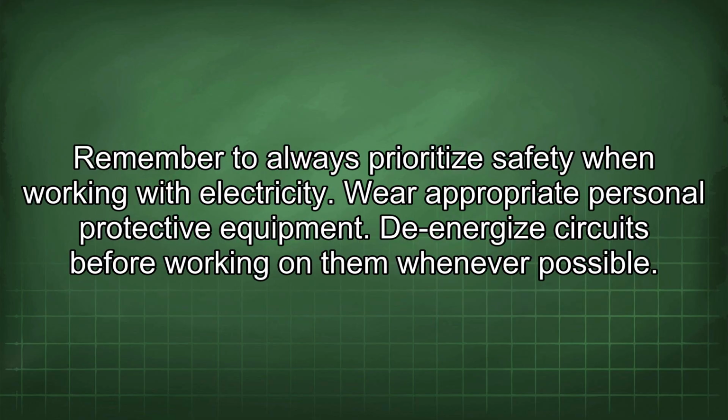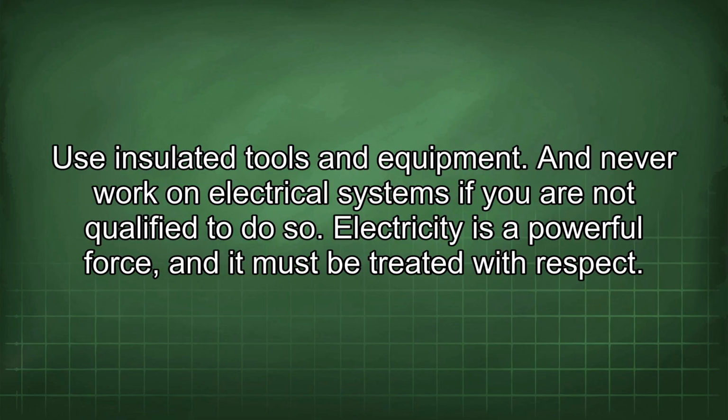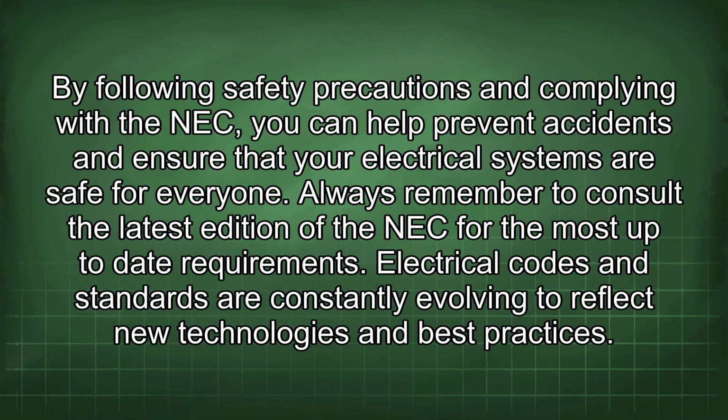Remember to always prioritize safety when working with electricity. Wear appropriate personal protective equipment. De-energize circuits before working on them whenever possible. Use insulated tools and equipment. And never work on electrical systems if you are not qualified to do so. Electricity is a powerful force, and it must be treated with respect. By following safety precautions and complying with the NEC, you can help prevent accidents and ensure that your electrical systems are safe for everyone.